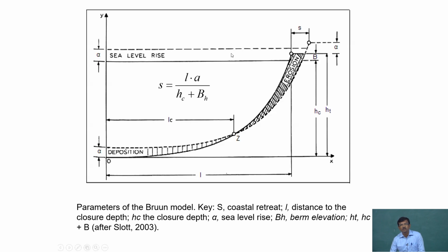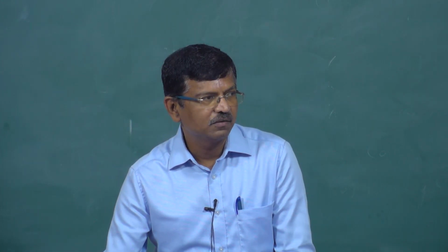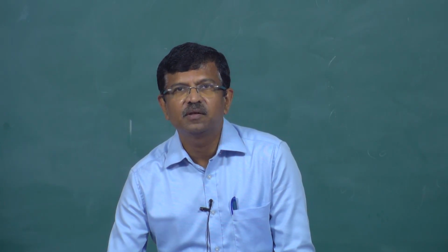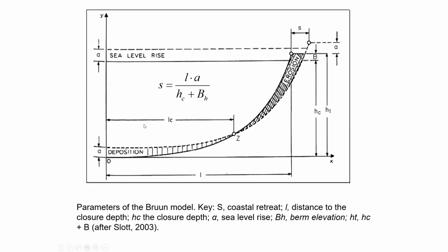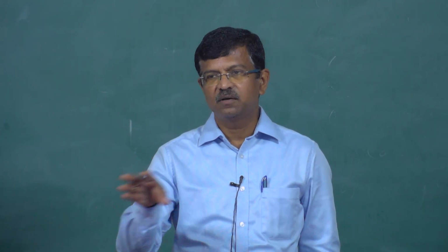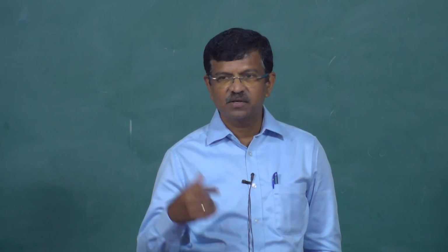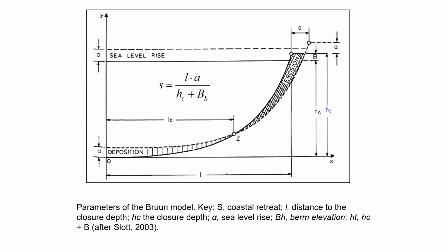When there is a change in the water level at an equilibrium stage, it always does that. If there is a change in water level and it stays for sufficient time, I will not make a definition of the time now, sufficient time, that means it will erode this part and it will deposit at the bottom part. So, there will always be an equilibrium of sediment erosion near shore or at the shoreline to the sediment deposition in the, I will not say deeper water, because deeper water in wave dynamics is different, but in morphological terms it is deeper water that will deposit.